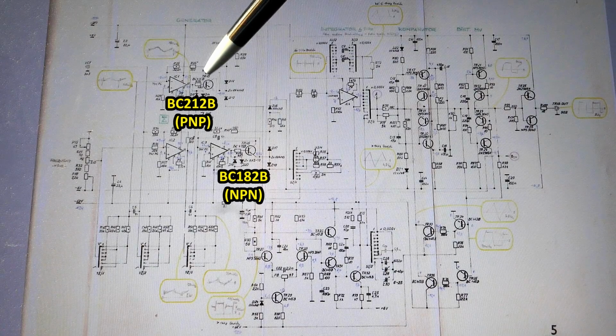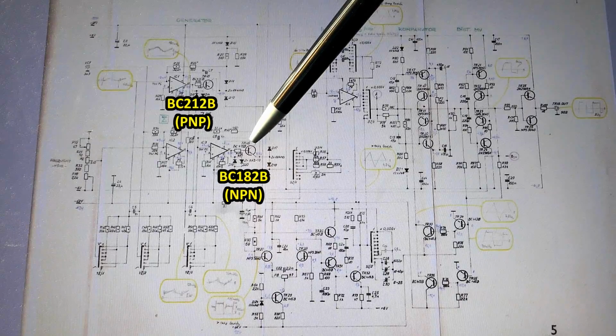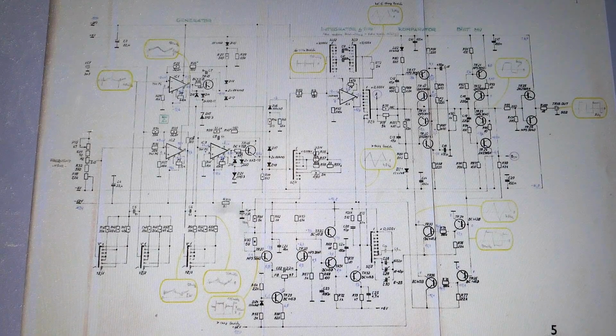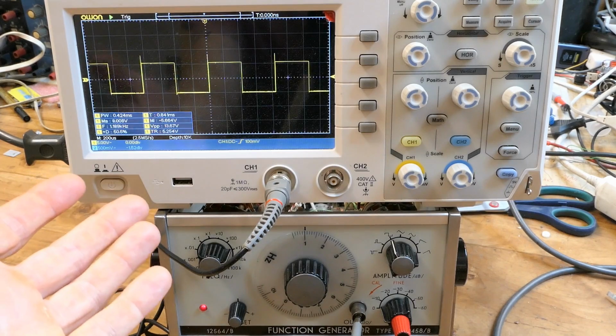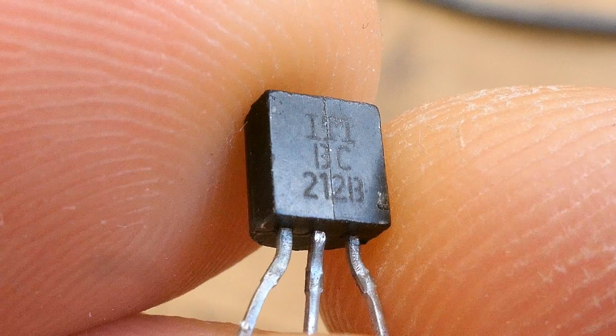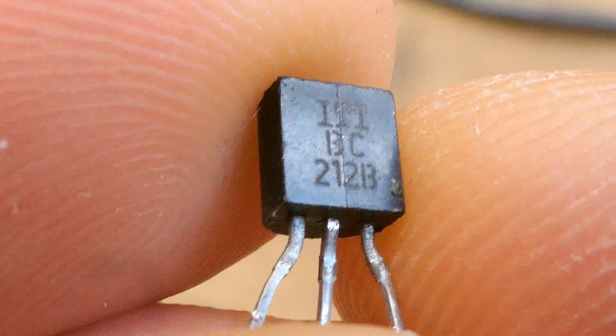And these two transistors are meant to be a PNP and NPN complementary pair, with very similar base to emitter voltage drops and a similar gain. Now it's almost right, and when I put a better suitable transistor into it, it will be even better, so let's call it fixed. And the original transistor looks somehow cracked.